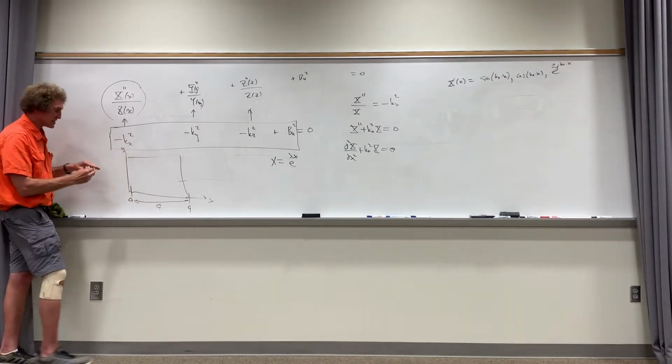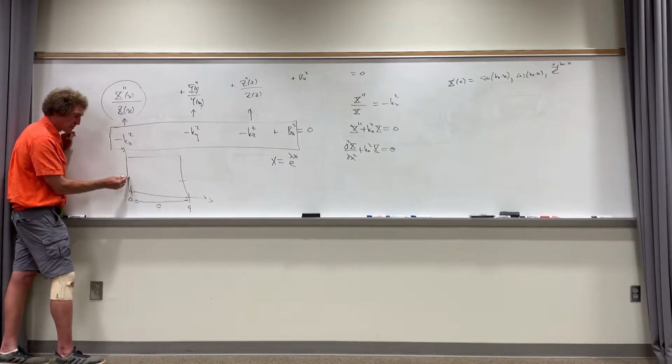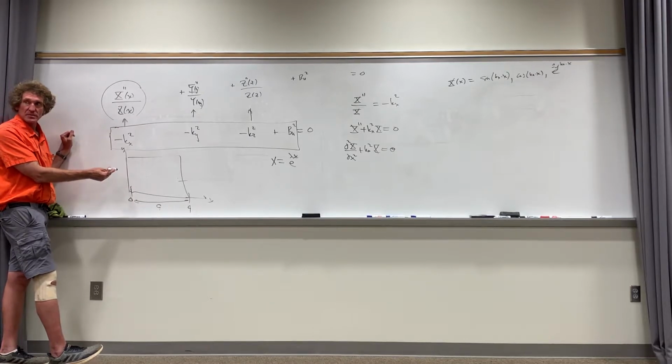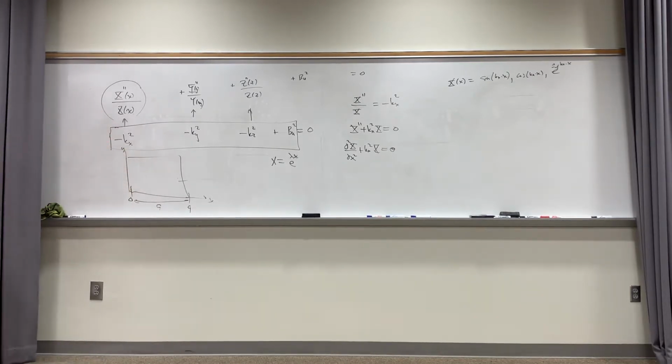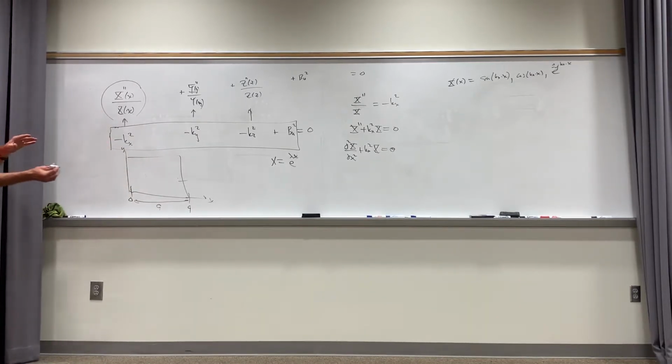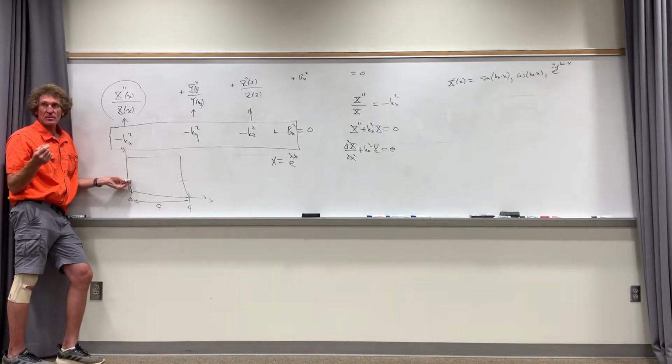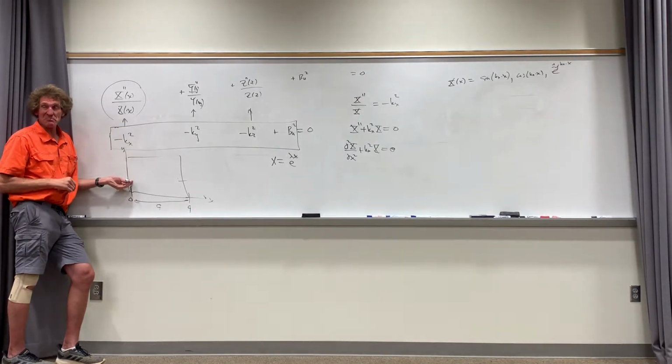All right, now when X is 0, the E field would be in this direction, right? Wouldn't that be parallel to a conducting surface? Because isn't this really a rectangular pipe coming out of here? It's conducting. So if Ez is right here and it's 0, well, is cosine of the argument 0, 0? No, cosine of 0 is what? Cosine of 0 is 1, right? That means no matter what the coefficient was in front of the cosine, unless it was 0, it wouldn't work.